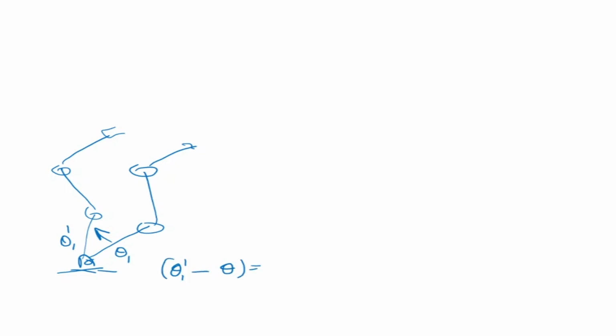It is generating an error and making this error go towards 0. So this is one input. What is the dynamics doing? The dynamics is disturbing it. For example, even if these links are not moving, or if these links are moving, the motion of the other links will tend to cause a disturbance on this controller on the first joint.